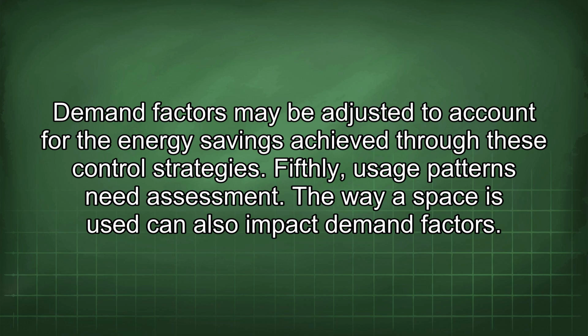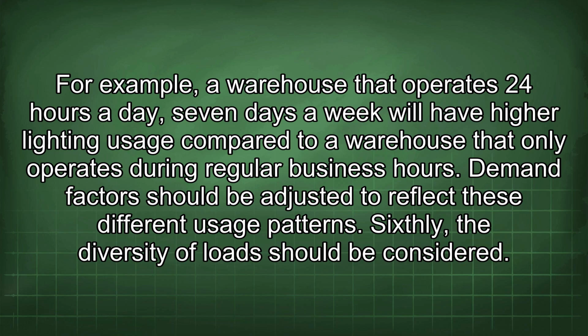Fifthly, usage patterns need assessment. The way space is used can also impact demand factors. For example, a warehouse that operates 24 hours a day, 7 days a week will have higher lighting usage compared to a warehouse that only operates during regular business hours. Demand factors should be adjusted to reflect these different usage patterns.